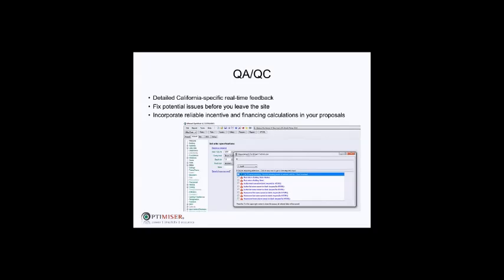If you click on any of the links, you can see there's a couple here. You have to enter a building street number. If you click on that, it would land your cursor in the building street number box, and you just start typing, and it corrects that issue. And when you clear the list, you get a Get HPXML button, and you can generate your HPXML file. You actually can't get the button until you clear the list.